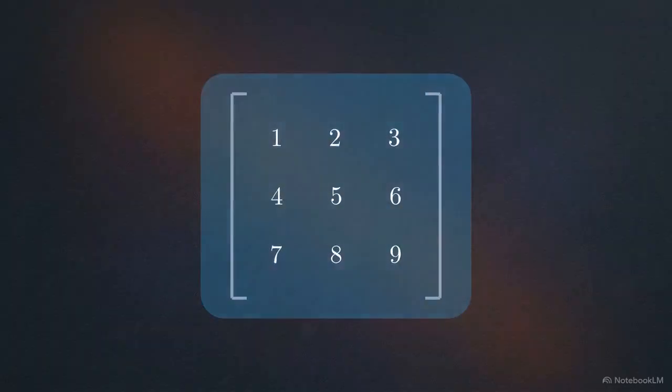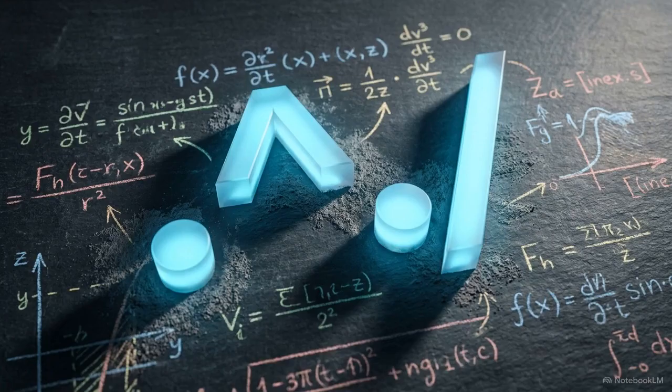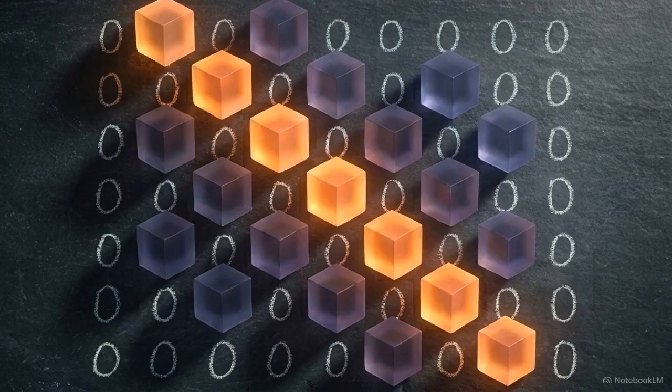MATLAB's default math is linear algebra, which treats variables as whole matrices. However, we need to perform operations, like squaring values, on each node of our temperature vector individually. To bypass matrix multiplication logic, we use element-by-element operators, dot-caret and dot-slash. This discretization creates a tri-diagonal matrix system. We then apply the Thomas algorithm to solve the temperature across all nodes simultaneously.